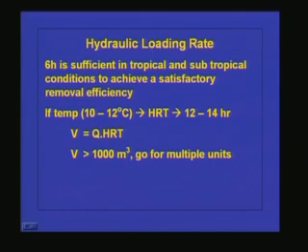Usually for the hydraulic loading rate, 6 hours of HRT is sufficient in tropical and subtropical conditions to achieve satisfactory removal efficiency. But if the temperature is low, in the range of 10 to 12 degrees centigrade, we have to provide an HRT of 12 to 14 hours to achieve the same efficiency, because we have seen that for every 10 degree fall in temperature, the efficiency decreases drastically.